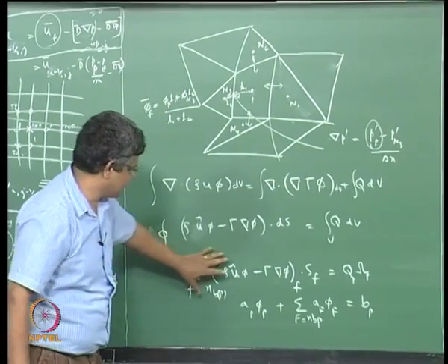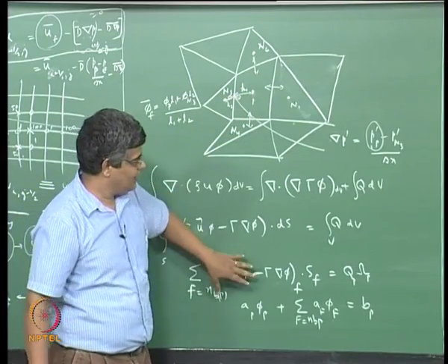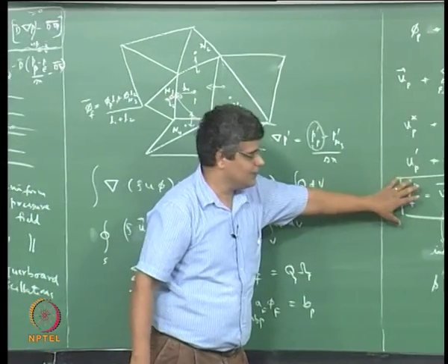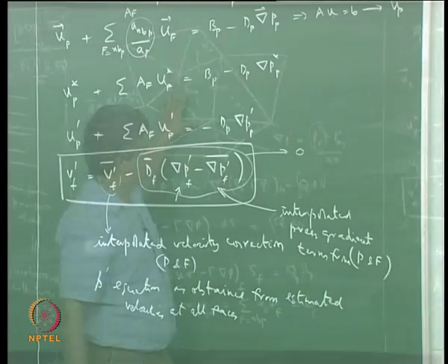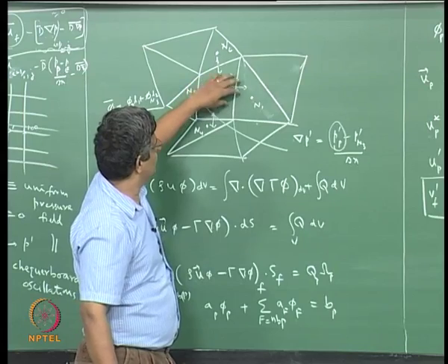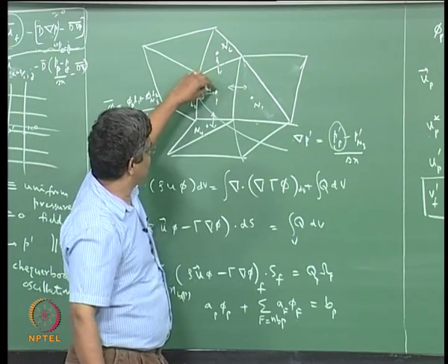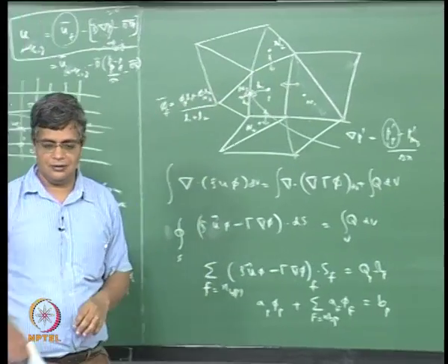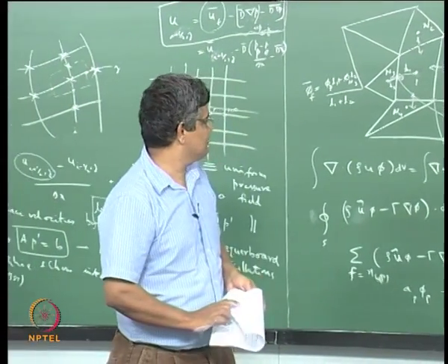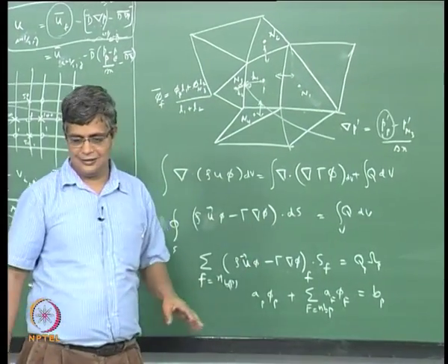This discretization is applicable for any number of phases, and same way the estimation of the phase velocity is also applicable for any number of phases, and together we can estimate all the velocity fluxes through each of the phases and determine the pressure correction contribution coming from that velocity contribution, and thereby we can extend this.